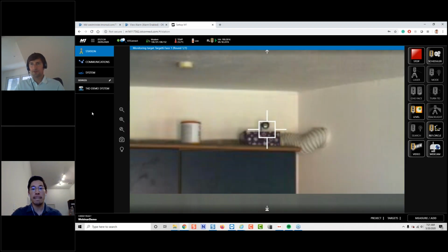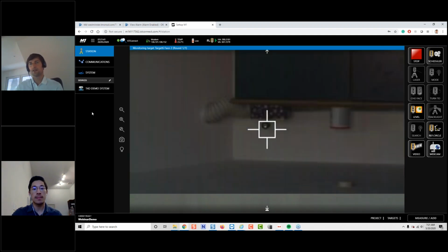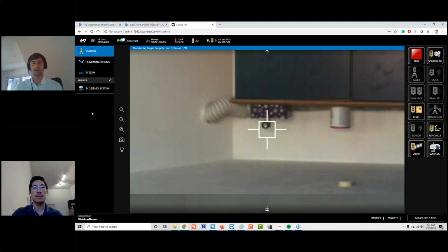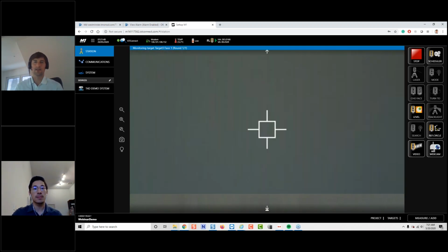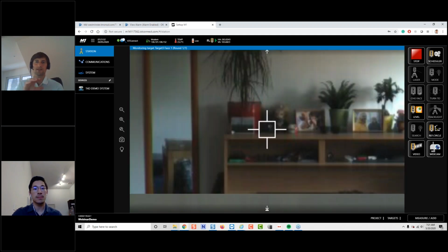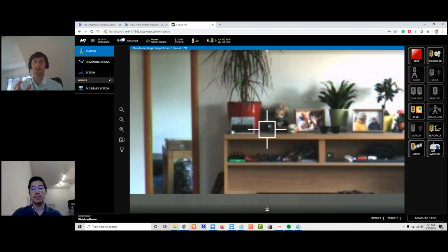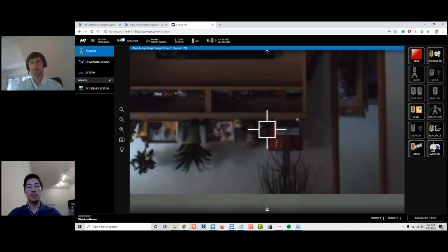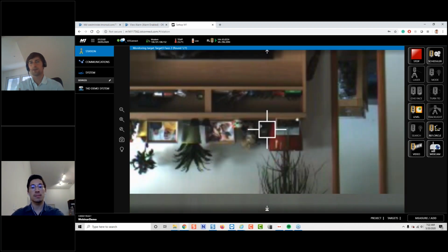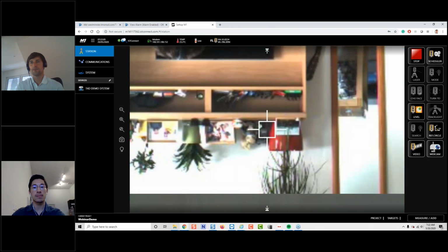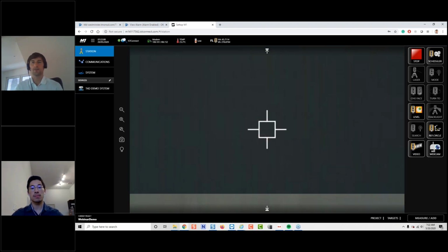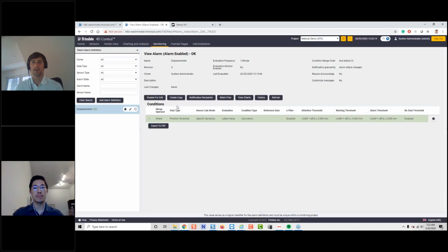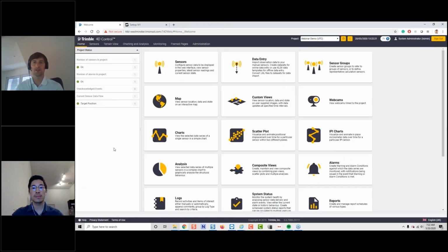Before we switch over to me again, the screen sharing, there is one more question that just came in from Stephen. Do you have to use the M1 to make changes to the S8 instrument? I think this is something we highlighted last time. The M1 is really a control device. It's not just a communication device, an advanced communication device. It also controls the total station, and that is why if you want to add, for example, a new target to your round, this is something you would need to do via the setup M1. That's correct. Only then T4D receives the observations to this target in the next step. Okay.